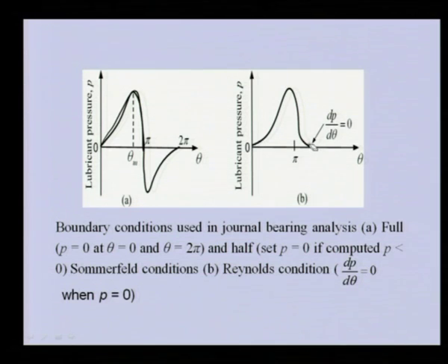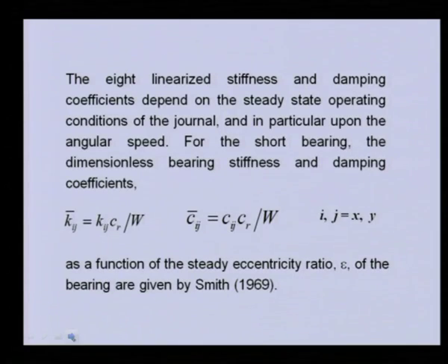So this particular boundary condition we need to use in the solution of the Reynolds equation, either using short bearing approximation or long bearing approximation, or even for the finite bearing approximation, which I will be describing subsequently. For short bearing approximation, I am giving the linearized coefficients directly without solving the equation as such.